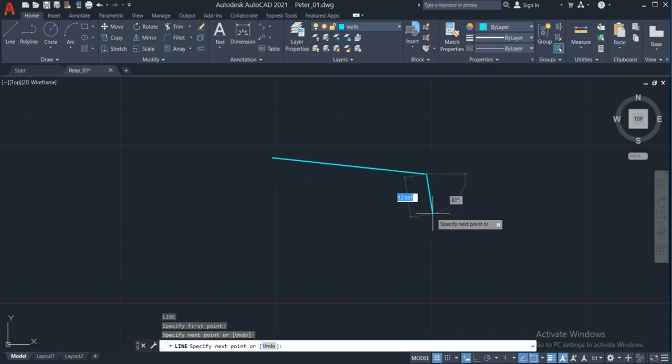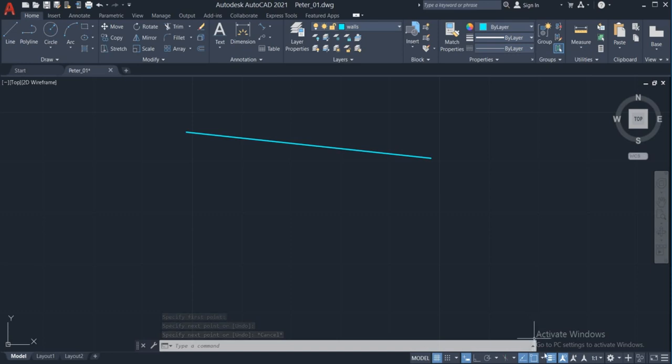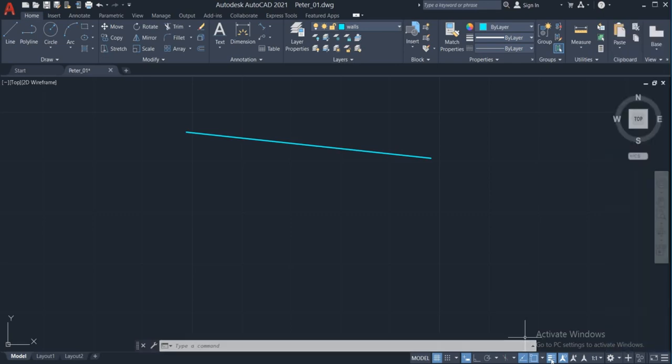What happened here in front of your eyes is that the layer has a thickness. How come you see the thickness? Because it is shown by the display of show and hide line weight. Can you see the show and hide line weight? If you can't see this, you go to the customization panel and check the line weight on and off. Once it is on, you can display the line weight. This is how you can see that the walls have a line weight in a specific way.